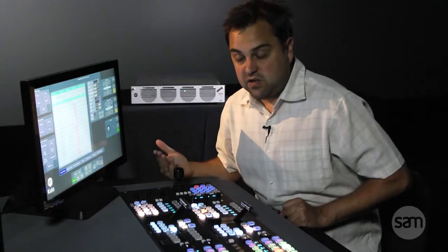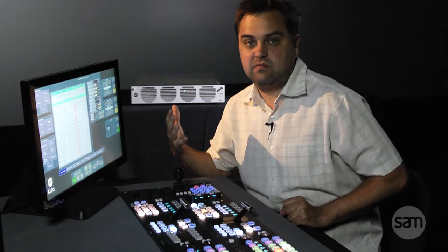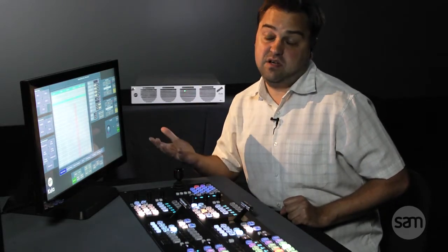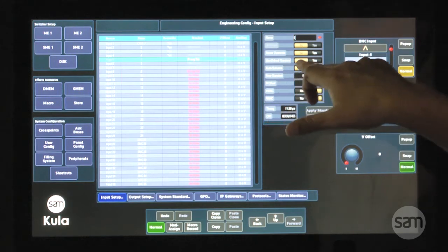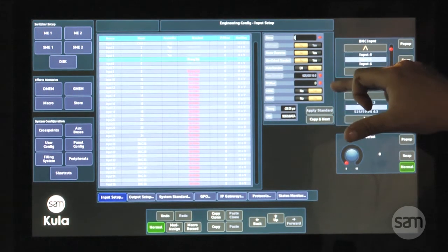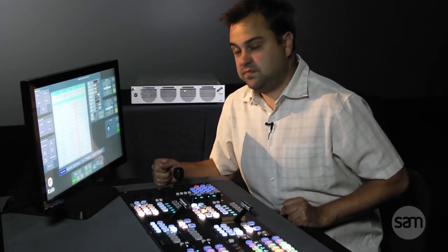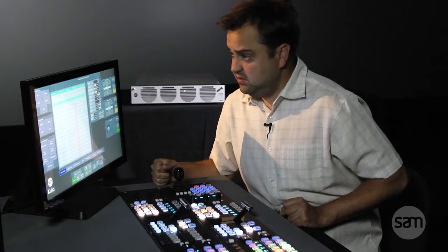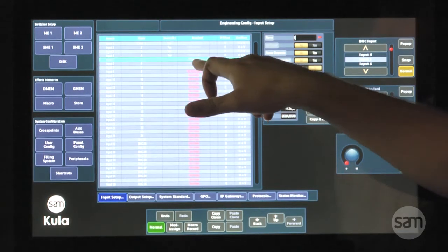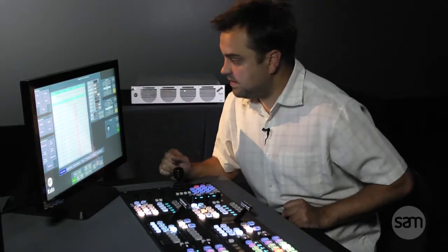But the majority of the time, we have something called auto standard, which also looks to see what's coming in, and it will up or down convert accordingly. So I would set use default to no, auto standard to on. And then it will auto detect the inputs coming in. You see now, it's changed that back to 1080i 5994, what is coming in.